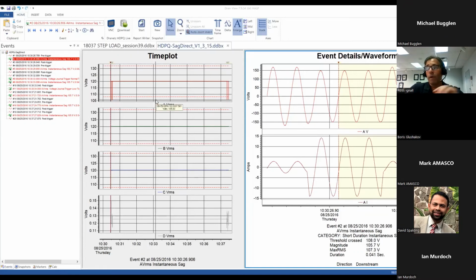So, in our CAN seminars, we have this in a PowerPoint presentation, but let's show you a live definition of what an upstream and a downstream sag is. What I mentioned before, the important thing when you have a voltage problem or a PQ problem is where did it come from? We talked about looking at the utility service entrance, but really the rules that I'm going to tell you here for sag directivity apply no matter where you're measuring, okay? Whether it be at the terminals of a load or at the utility supply. The utility supply just defines responsibility here.